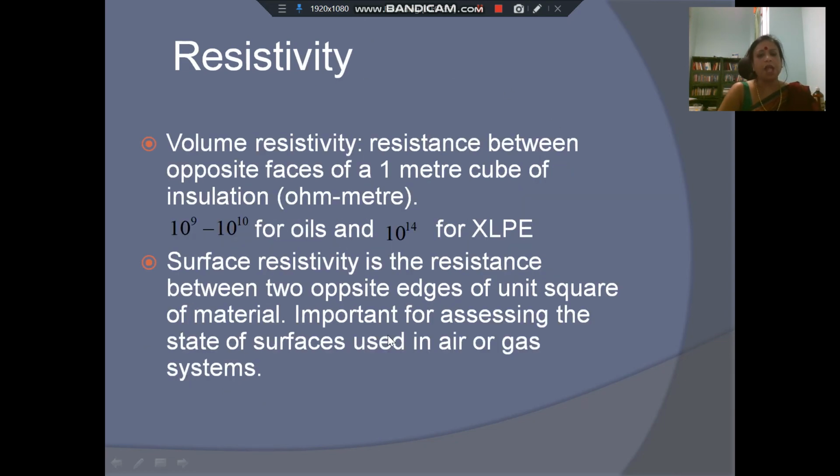Though I have already talked about conductivity, there is one more point that I want to make about resistivity or conductivity. It is the same thing. Now, in talking about dielectrics, we talk about two different kinds of resistivity: the volume resistivity or conductivity, and the surface resistivity. The reason is that when we are talking about a conducting material, when you apply a potential difference across two points, most of the current will flow through the inside of the material, through the volume of the material.